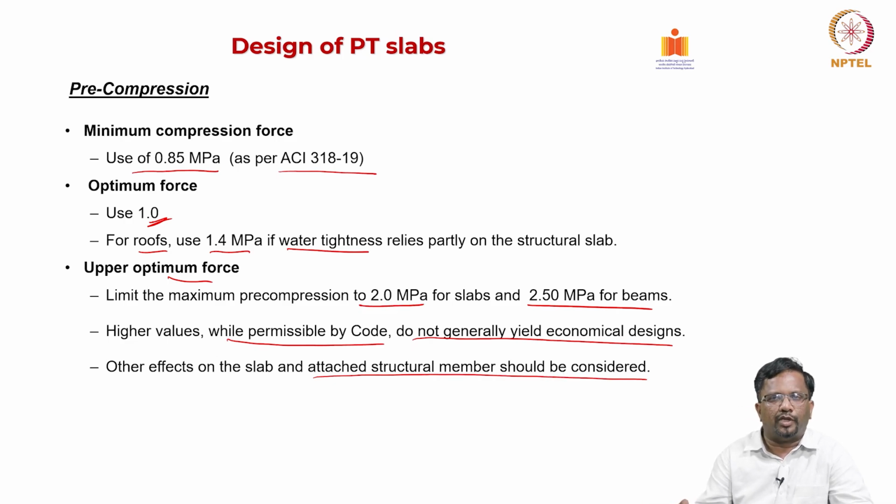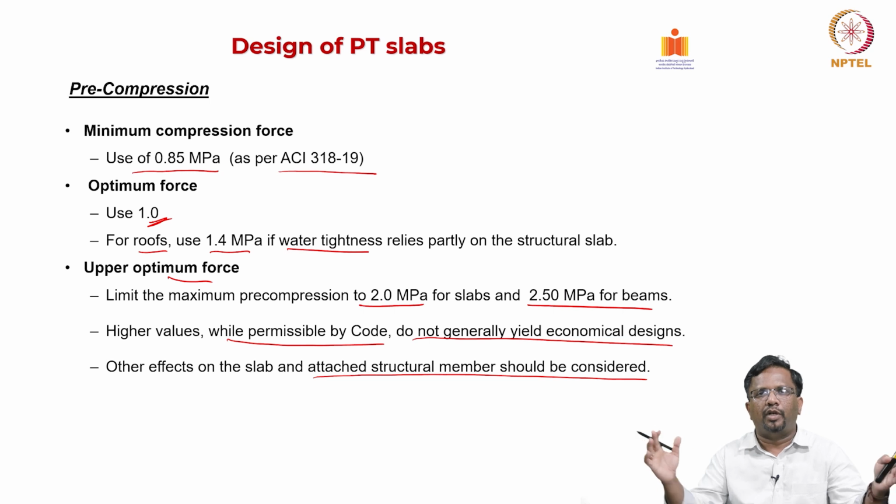For example, while you do the pre-stress, let us say you have a shear wall in the middle. Then that will also produce some restraint, and because of that you will develop some hyperstatic effects. All those things have to be considered in your design.